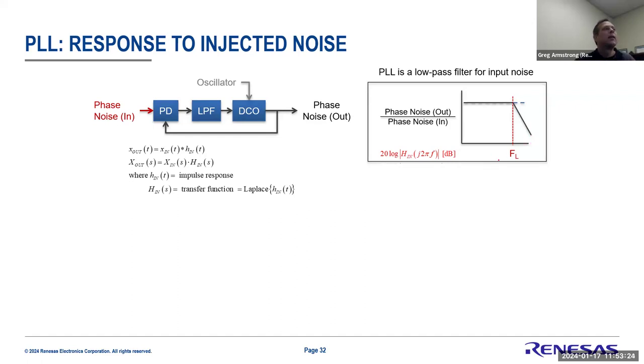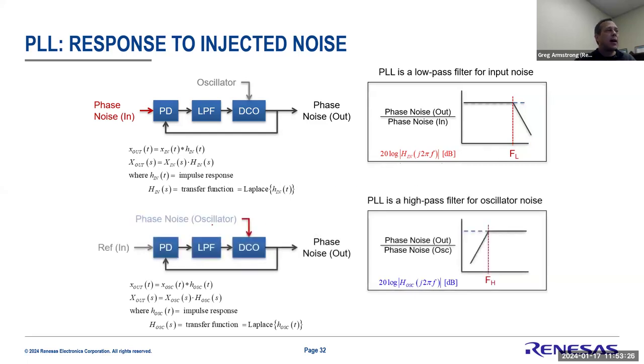If you're looking at it from the oscillator standpoint, one of the characteristics of a phase lock loop is that although the closed circuit is trying to follow the input reference, any noise variation that happens to your local clock itself passes to the output as what we call high pass filtered noise. That means if you have a very quick change of your local oscillator, you're going to see it immediately on the output because there's no way to filter it.